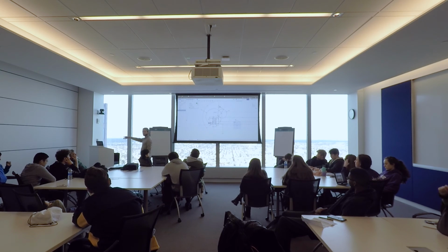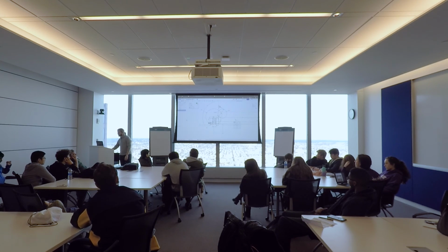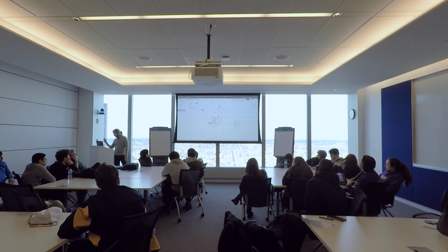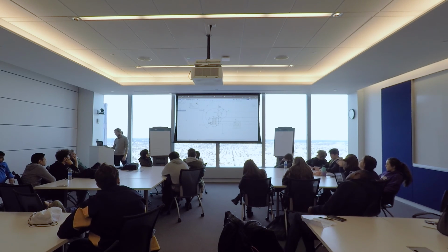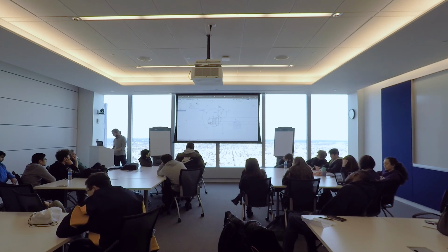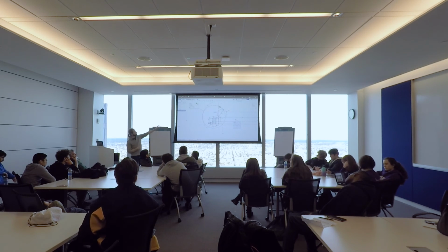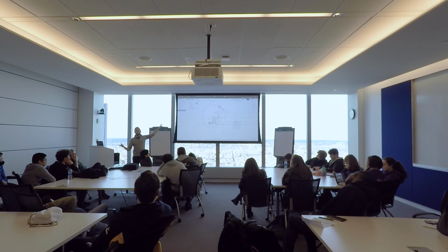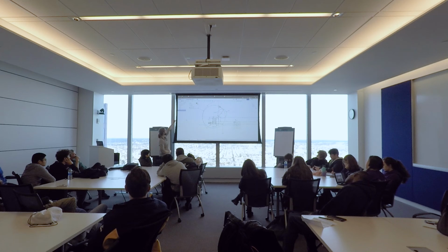And now you can come in here and let's put in a different cylinder. Let's say instead of 7 inches, it's a 10-inch extended cylinder. And I'm going to do 10 times 2 so that I can automatically. What I would normally do is make a variable for this, and I would automatically have an equation in here that would multiply it by 2. So I could just update the value, the stroke of the cylinder. That would make it a lot easier.